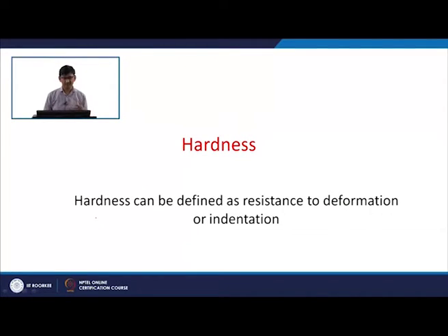Now these were the NDT techniques, and now we will come to another part, okay, one of the measurements which we could not cover earlier in mechanical properties, that is the hardness, okay. This can also be considered a kind of non-destructive way of finding out a mechanical property, because you just put an indentation on the surface, okay, rather than doing a tensile test to find out the mechanical properties of the material, okay.